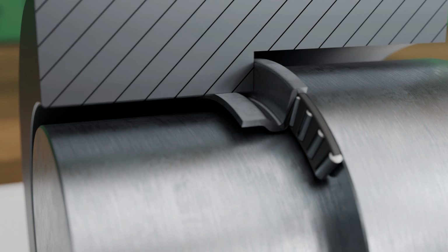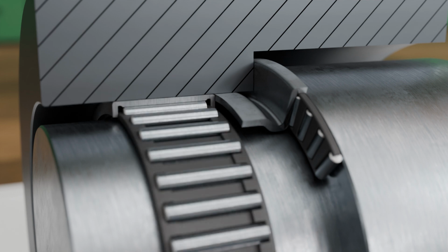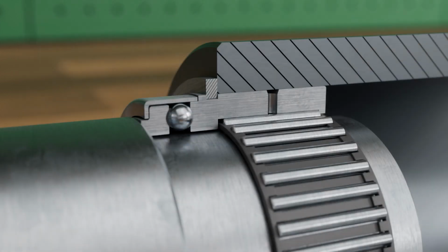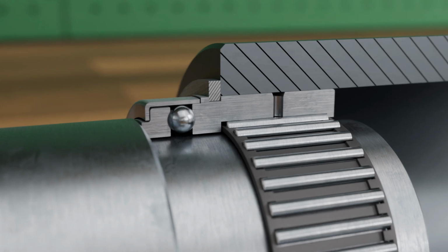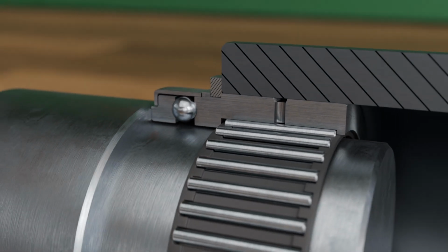To support a simultaneous radial load, this thrust needle bearing can be combined with a radial drawn cup needle bearing. In the case of direct mounting, the shaft surface must also be ground and hardened. Alternatively, a radial needle bearing with an inner ring can be used. In special bearing designs, axial and radial bearings are also combined and supplied as ready-to-install bearing sets, for example needle axial ball bearings. These enable the absorption of very high axial and radial forces while maintaining a compact design.